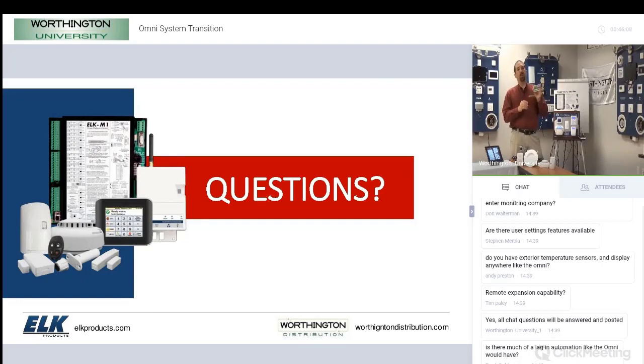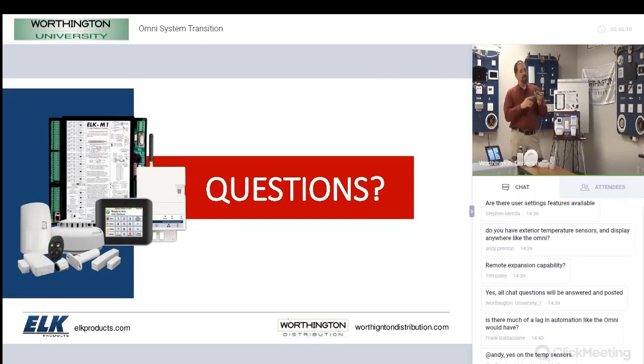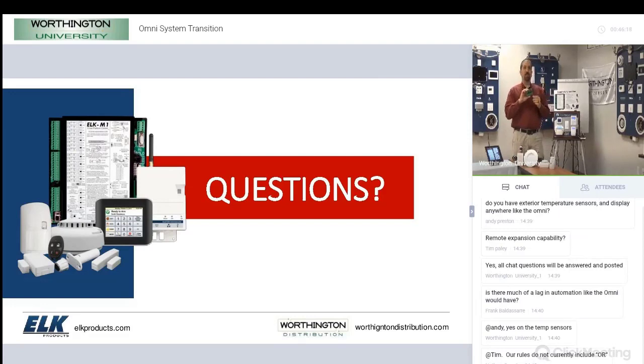You go from one keypad to the next, to the next, to the next back. When you don't have that set up as a daisy chain, you would have this retrofit hub, which would create that daisy chain through your home run wiring. So one thing to watch out for, if the house has already been pre-wired home run, you definitely want to make sure you add that.